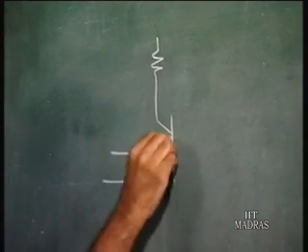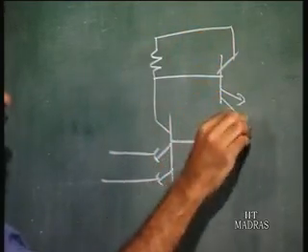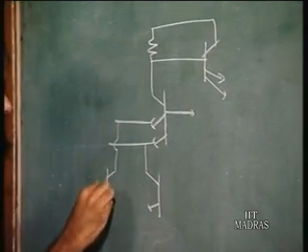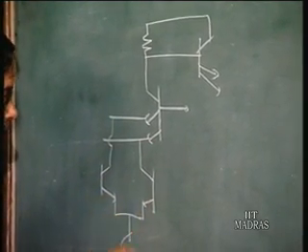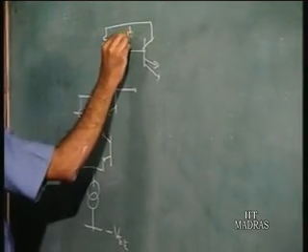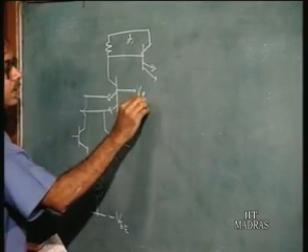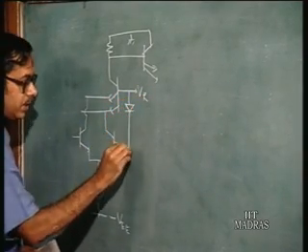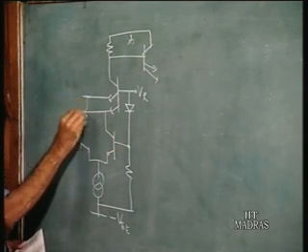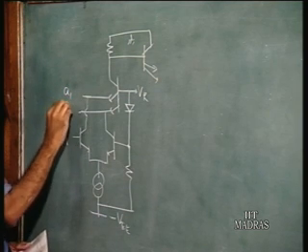You have a multi emitter transistor, this is the output side, and then you have the emitter couple structure here, the current source, this is minus VEE, this is ground, and here this is VR, then you have a level shifting arrangement. So, this is VR minus V on, and you have the inputs, this is A, capital A, and this is small a1 and small a2.